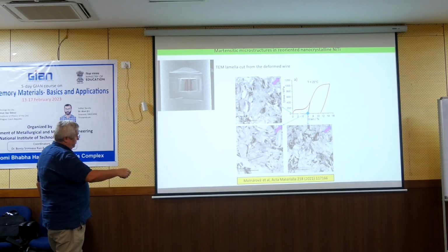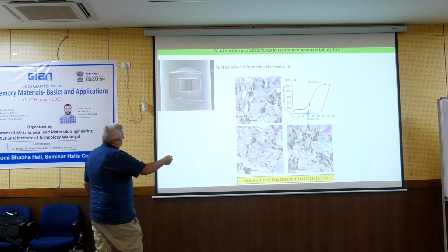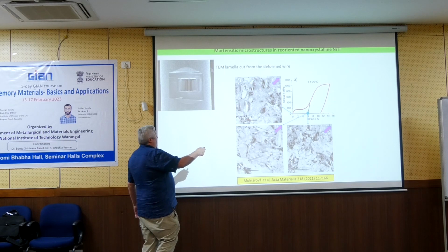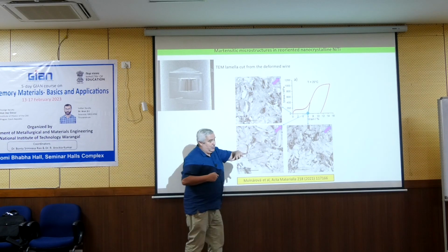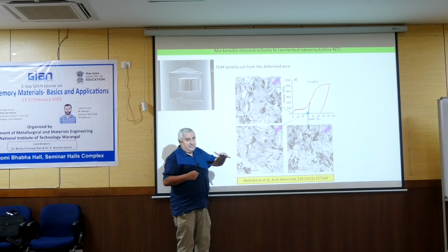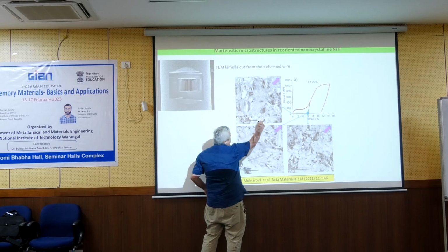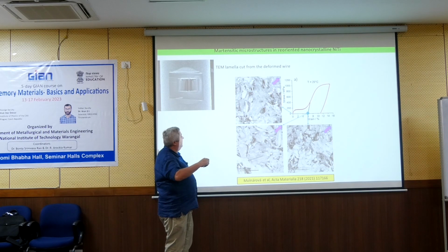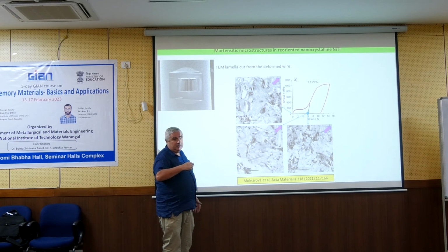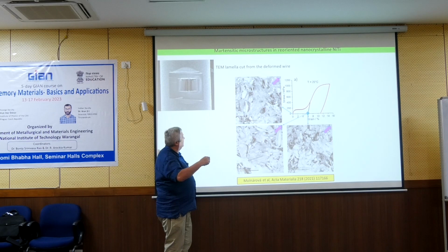So again, this is the stress strain curve, and this is how the microstructure looks before the test. You don't see much. This is because in electron microscopy, if you want to analyze maybe this grain, you have to rotate everything suitably. Because the next grain is differently oriented, if you take a bright field from a white area, you will not see anything. That's not possible by just taking a bright field.